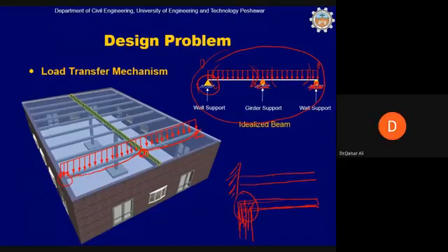Okay, so idealization of this extreme end, when this is a hinge support, this is clear. But if we also idealize the intermediate support as hinge support, then you should mind that the idealized model should represent as closely as possible the behavior of the physical structure. This is the idealized beam model. So what is the physical or actual behavior of the structure? The beam will come down, and the beam cannot come down at this point.